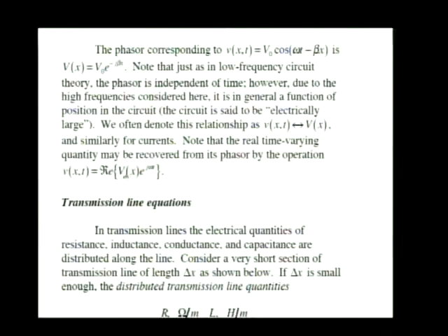All right, we've got the real part of e to the j(omega t minus beta x): cosine of (omega t minus beta x) plus j sine of (omega t minus beta x). We want only the real part. What's the real part? Well, that's just the cosine part. The sine part was multiplied by a j. So the real part would give us exactly what we're looking for, cosine of omega t minus beta x, and we'd recover the original time-varying signal by performing this operation.